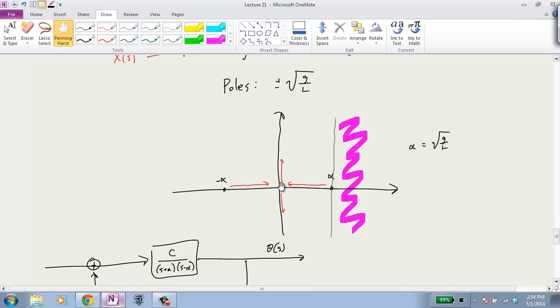But if we work out the math for the same reason, by adding proportional feedback, we're only going to cause the poles to go up and down the imaginary axis. And it won't actually make it stable, so we can try something like that. We'll just use K1. And if I remember right, I don't remember the values that work well here, so I'm going to keep it not too big. Okay, so now it should try to recenter, but only using proportional feedback. So again, we should see the same sort of oscillation going on.